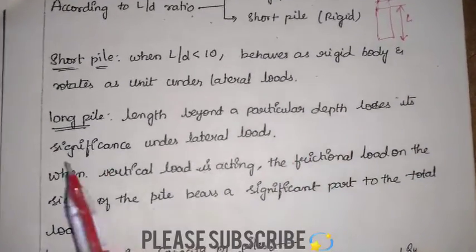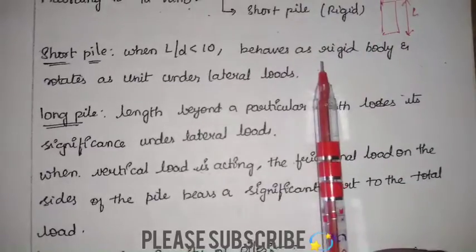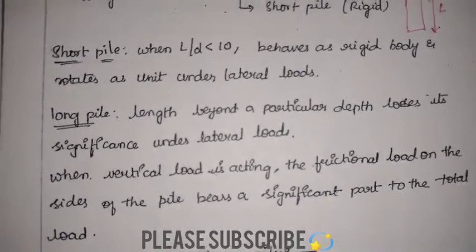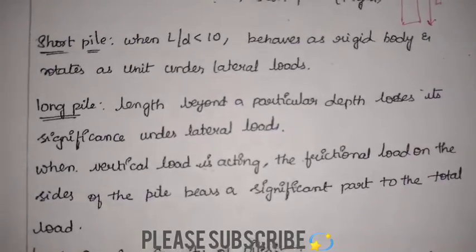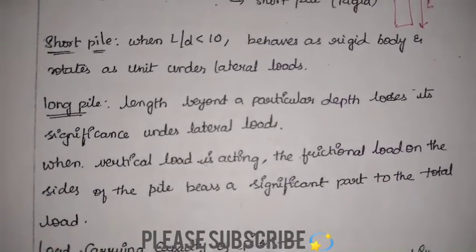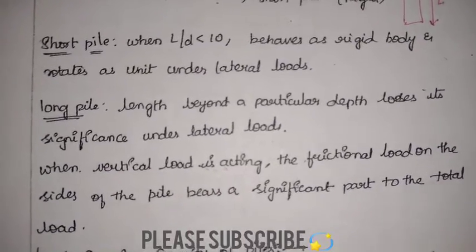Next comes the long pile. The length beyond a particular depth loses its significance under lateral loads. As the L by D is more, the lateral load is significant only up to a certain depth. After that, the pile is not much affected by lateral loads. Whenever vertical loading is acting, the frictional load on the sides of the pile bears a significant part of the total load. So in this case, the vertical loads are the main term to be considered.